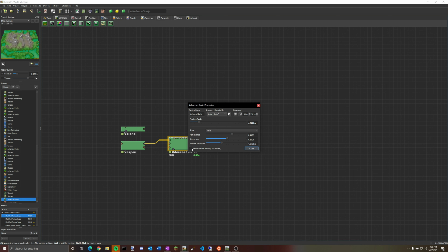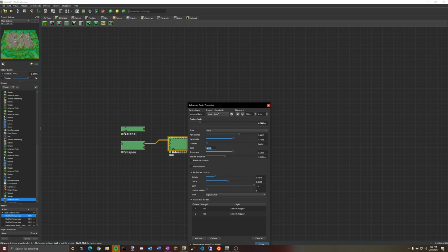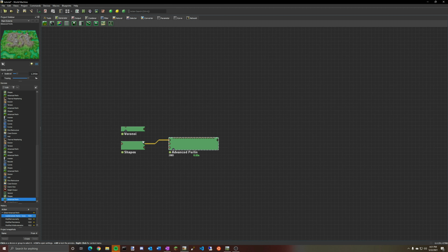And then of course you can go to advanced settings. You can set the seed if you want a completely different random input. You can set the steepness, which will make it steeper or flatter. Another important one is the middle elevation that lowers or raises it. The persistence, again, makes it more flat, basically. This one expands it and contracts it, similar to the feature scale. And the other ones, you can just mess with it until you get it to look like what you want. So, yeah, those are our main generators.